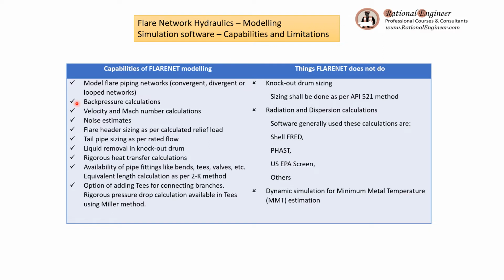It can perform the back pressure calculations, the velocity, Mach number calculations, estimate noise. Option to size the flare header with relief load, whereas tailpipe with rated flow. It can remove the liquid in the knockout drum device. It can perform rigorous heat transfer calculations.